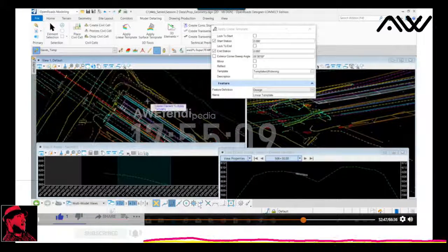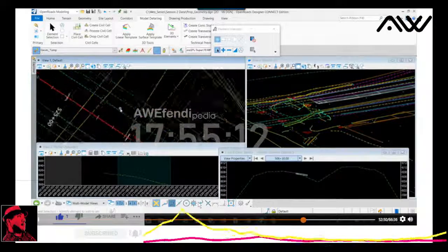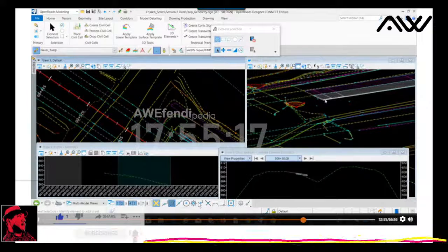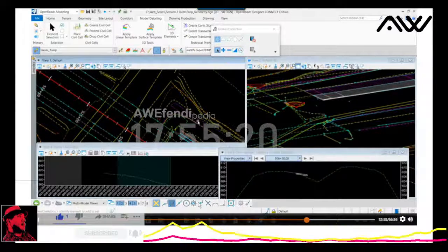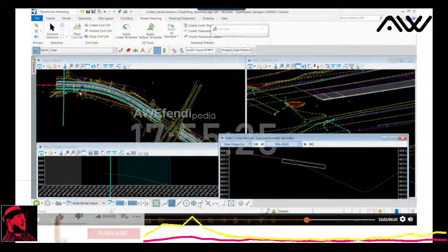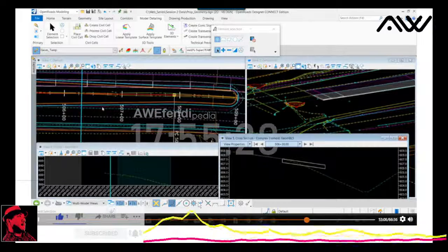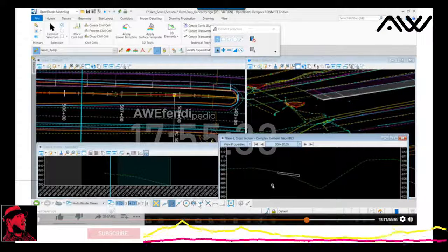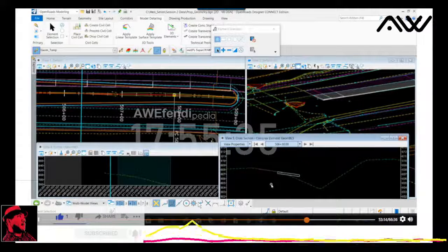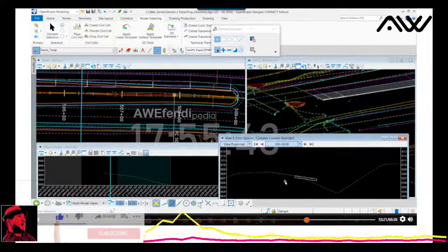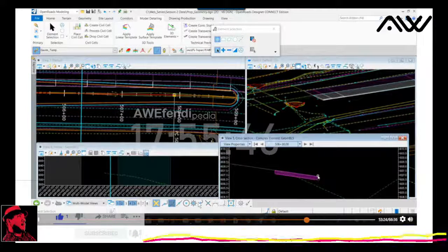We can even, well, we won't worry about the bridge at this point. I'll project it in a different way. But we now see that PGL based off the existing cross slope and widened. Now, I will point this out. In this case, for time's sake, we did not take into account, although we may do this at a later session in a SIG coming up, super elevation correction or milling and overlay. Again, our focus is geometry, so we didn't go through that process. We may pick that up at a later date in a separate, maybe SIG session. But we've located now this point that's going to be the basis for what will become our PGL.